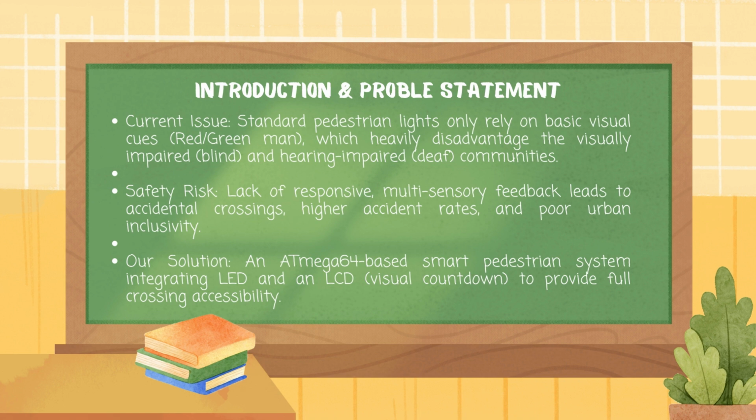Therefore, we designed an intelligent pedestrian crossing system using the ATMEGA64 microcontroller. Our system includes a push button, an LCD countdown display, and traffic light LEDs. These features make road crossing safer and more accessible for everyone.